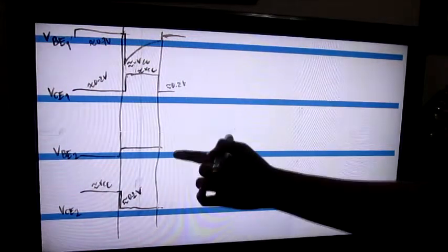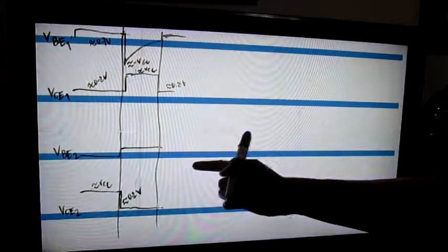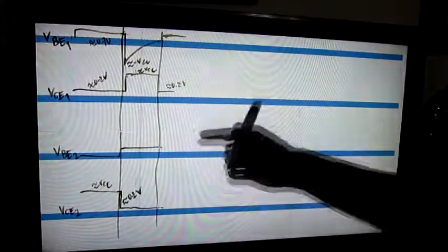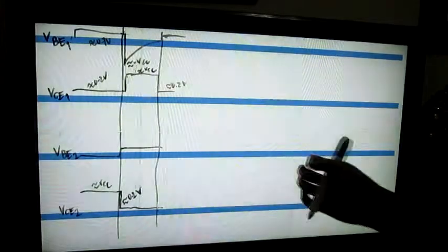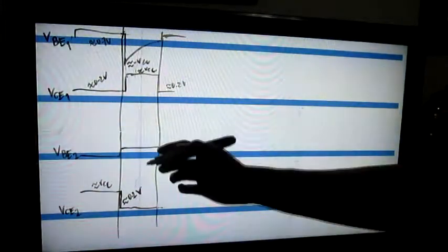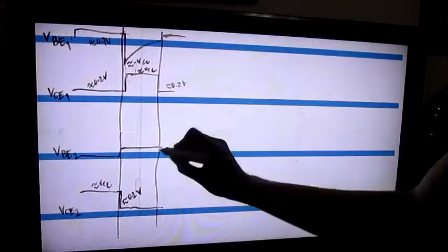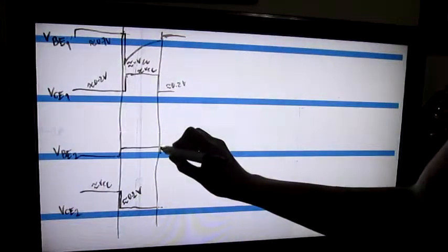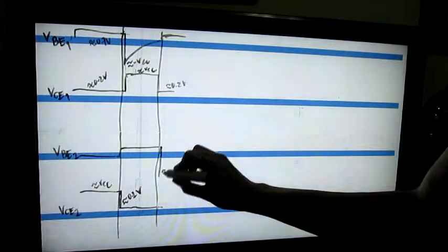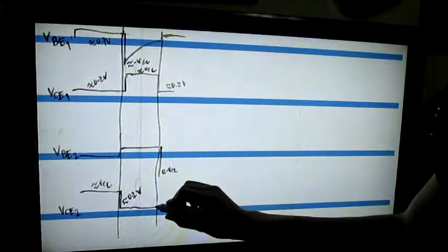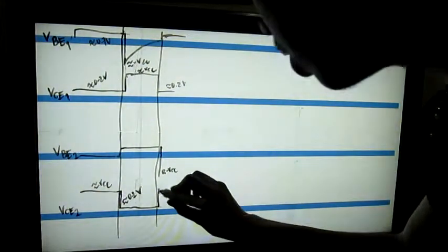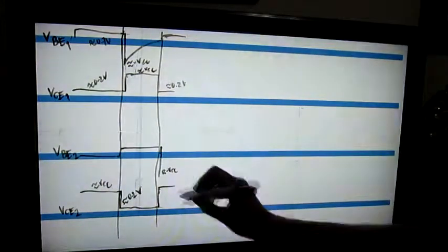With that, the voltage between the base and emitter of Q2 becomes equal to the voltage of capacitor C2. In this section, capacitor C2 is charged to around VCC minus VBE2. To simplify, we will just assume that it is equal to around VCC, so its voltage is plotted here as around negative VCC. At this instant, the collector to emitter voltage of Q2 rises up to VCC since it now operates in cutoff.